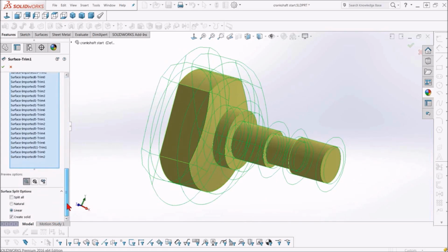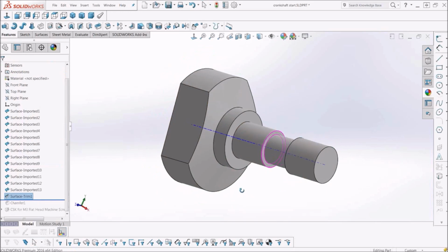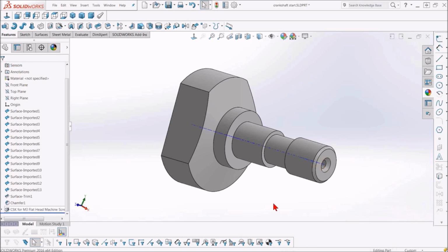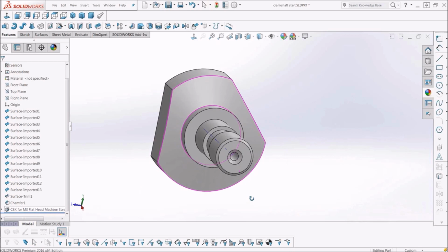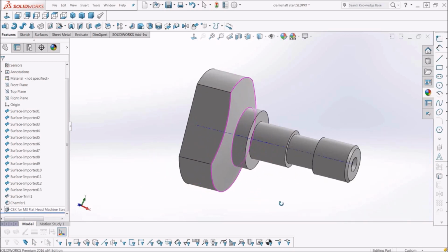Also, sometimes the CAD software may have a little checkbox that says, after you've gone through and trimmed all these, go ahead and create a solid model. So when this is done, we actually have a solid model now that we can go through and use functions like maybe I'll put a chamfer out here on the end, and also with the very end, I'll go in and put an M3 flathead screw cutout inside. So I've got all of that set in.